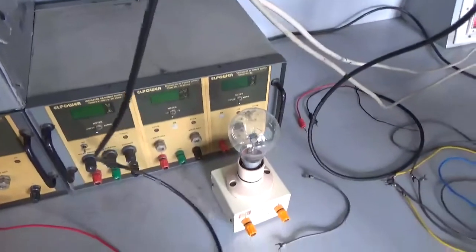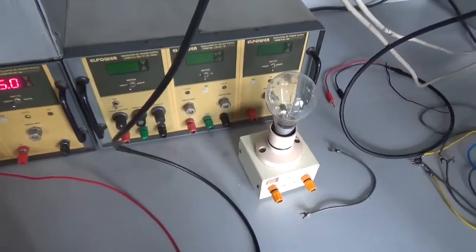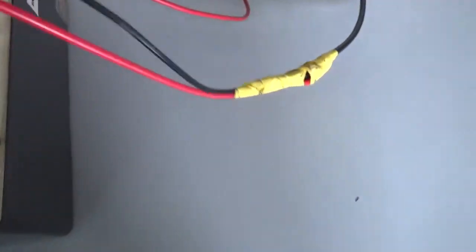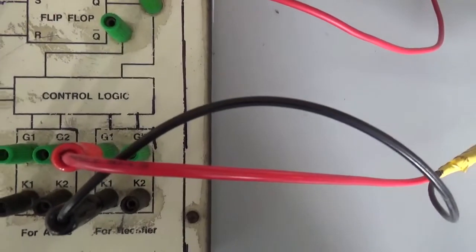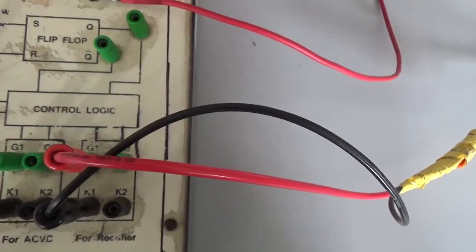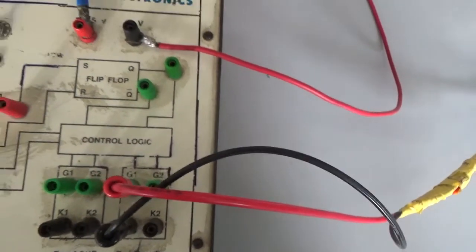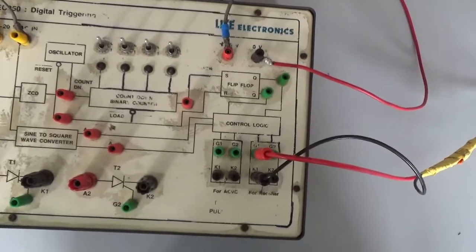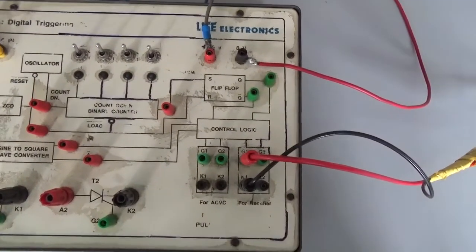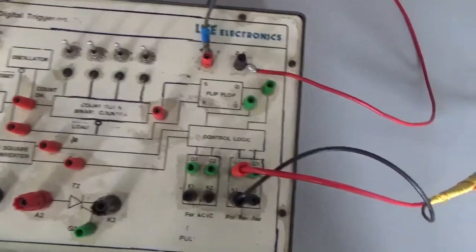Let me show you the pulses at the G1 K1 of the rectifier. So what is G1 K1? These are isolated pulses. In the control logic, you have a chopping circuit as well as the isolation circuit. Isolation circuit is going to isolate your power circuit from the control circuit. This is our control circuit. This control circuit has to be isolated from the power circuit because the control circuit is very costly compared to the power circuit. So many electronic gadgets are there.